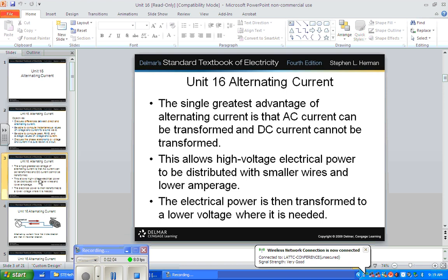A lot of businesses have backup generators. Hospitals all have backup generators, and sometimes they have backup generators and UPS systems, uninterruptible power systems. So they're making their own power, and for that first minute or two while the generator's starting, everything is carried off a set of batteries on a UPS system.